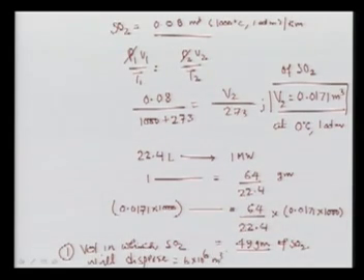And the second thing we did was find the mass of SO2 that got emitted, and we found that to be 49 grams. So, you have the mass of SO2 and you have the volume in which it dispersed. You can find out the overall concentration of SO2 in the volume in which it got dispersed, and do not forget that there is a village sitting in the same volume.